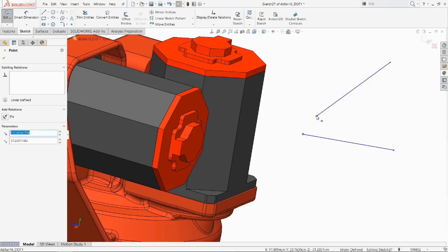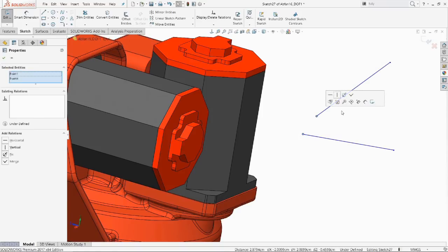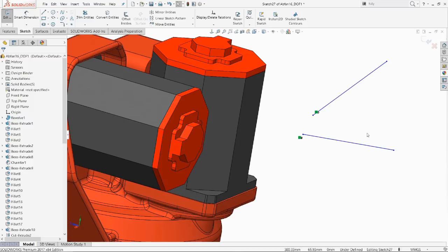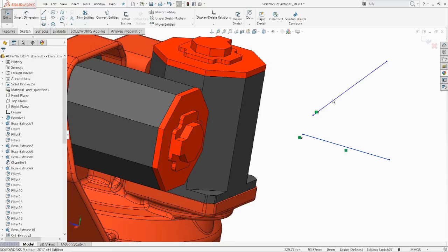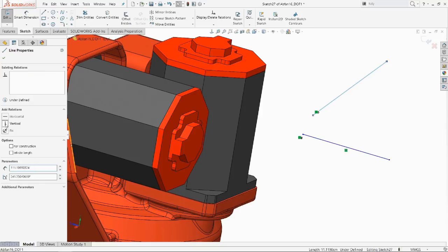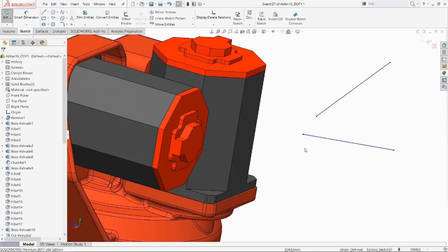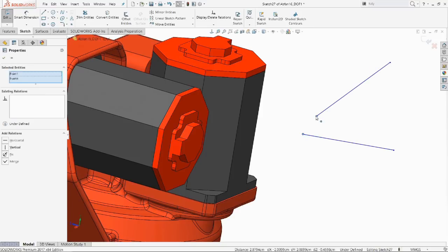The functionality that's been there for a long time is over on the left-hand side, the properties. It actually will show in bold what it was closer to, for lines in particular. But then added, I think in SOLIDWORKS 2015, was that dashed box around it. So it's a newer addition to the tool. People ask, hey, what's that box around there? Well, that's what it is, right? Click the 2 points. There we go. I'm going to make vertical.